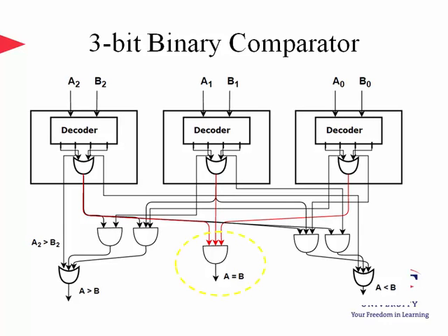Let us walk through it, starting with the equality case. Here, what you see is the case implemented using an AND gate, where all bits are equal, and they have to be equal at the same time. The connection for this case is shown with the red wires.